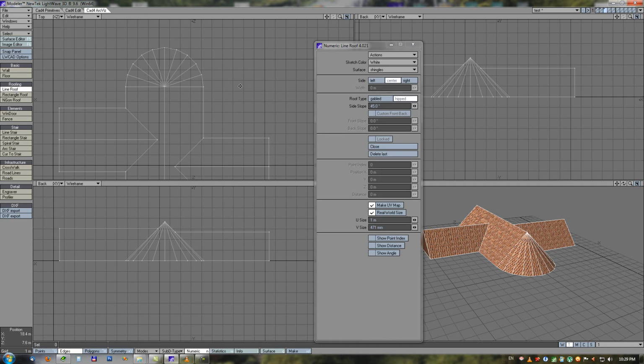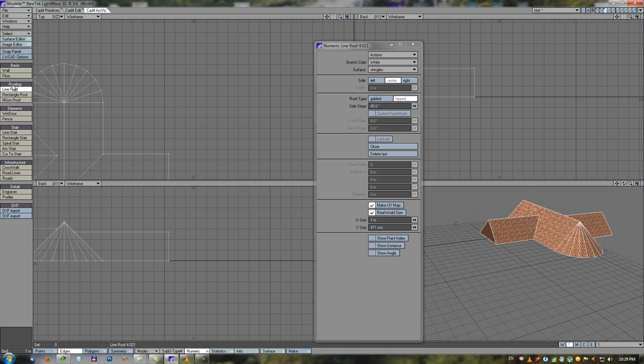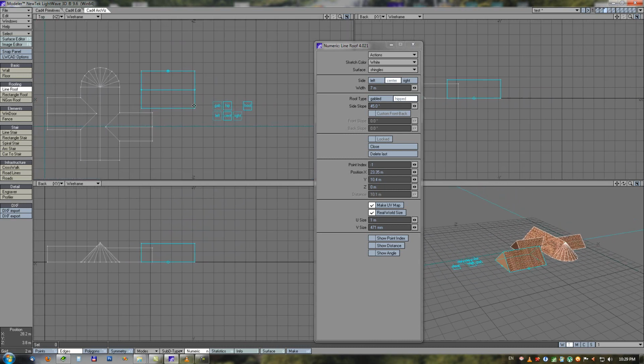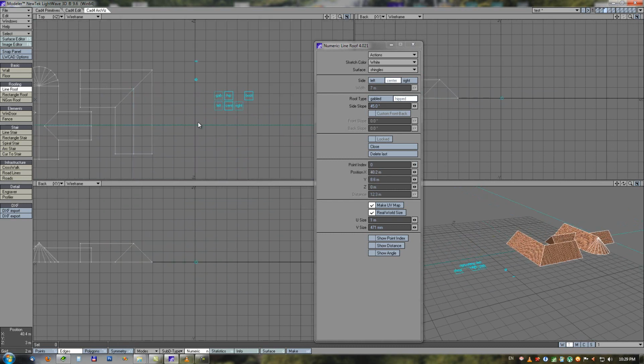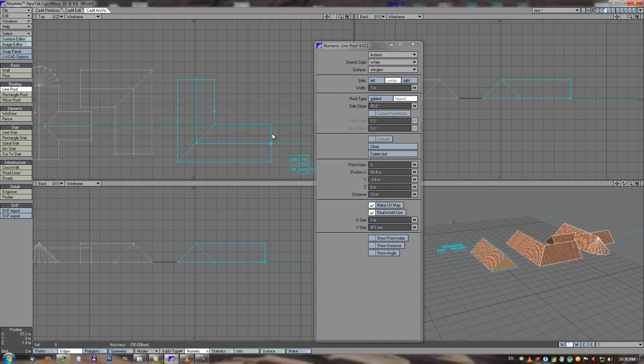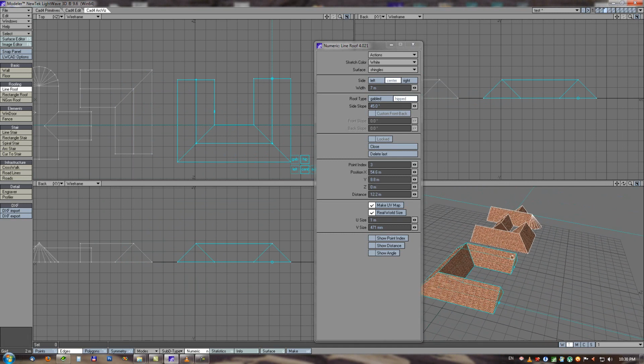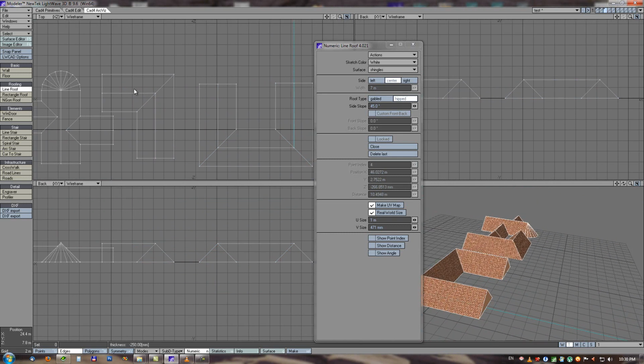And first, the line roof tool. This is a new tool. This is based on a line tool template, and with this tool we can create directly any L shape or U shape or S shape or any shape type of roof directly, and together with booleans.